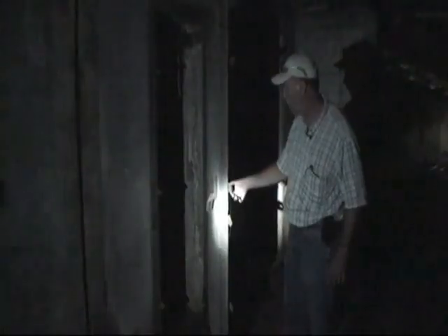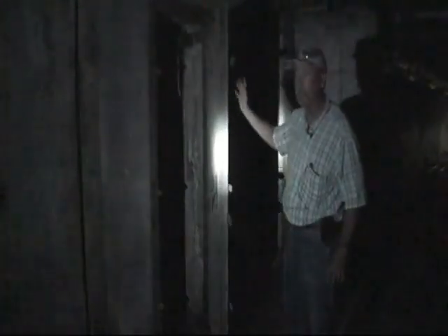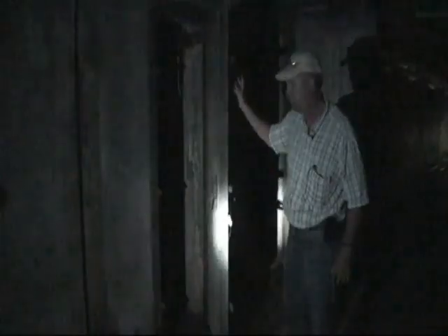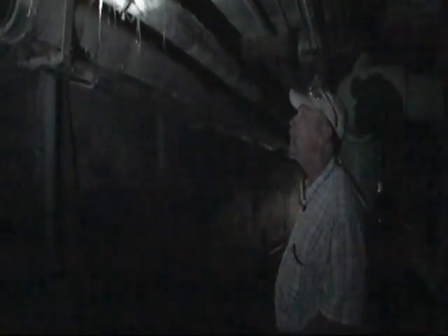Typically, when people take these off, they will essentially remove them from the hinges and dispose of them intact without disturbing the inner core. Something else to keep in mind when you're looking at long runs of piping, even though the material may appear to be replaced or intact, or it's a new fiberglass material, it's not at all unusual to find lengths of newer replaced material overlain by patch material to asbestos material back to fiberglass again. So you need to be sure and examine the entire length of the pipe run that you're looking at.